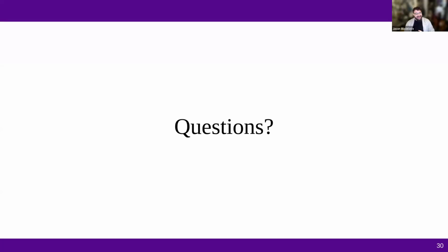Yep. Yeah, that happens a lot. Ultimately, that's one of the things that benefits from a person being in the loop, being able to evaluate, is this completely off the rails? But also, like I said, we just submitted an updated version of AutoChip that kind of seeks to answer that a little bit. A very brief overview of what that looks like: we actually generate multiple candidates per iteration, and then we rank them based on how well they're passing the test benches or the compilation. And if we have something that passes 80% of the test cases off the bat, we know that it's better to follow that than the thing that couldn't even compile.